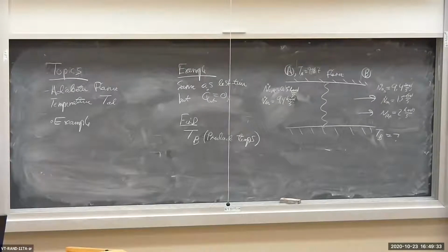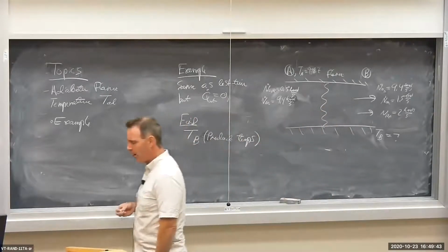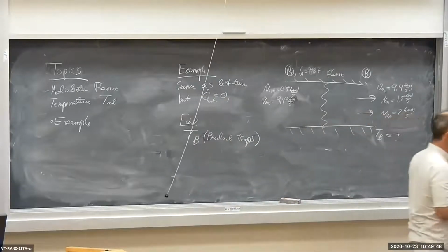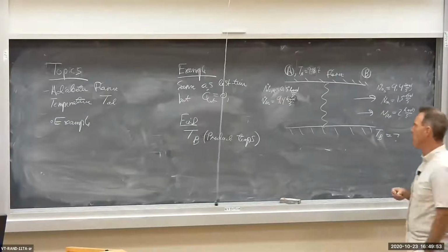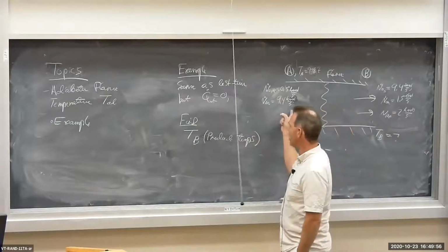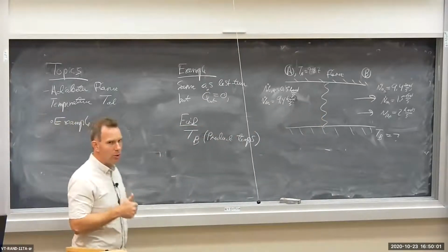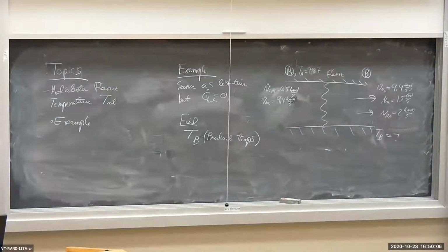Instead of having a heat transfer with a known exit temperature at the combustor, we're going to insulate the combustor. So the combustor is a channel, a duct. We're going to mix the air and the fuel together, we're going to burn it, but we're going to wrap the duct and the combustor with insulation. So we're going to set Q dot equal to 0. No heat transfer. So all that heat is released and results in a very large temperature increase of the mixture, producing very hot product or exhaust gases.